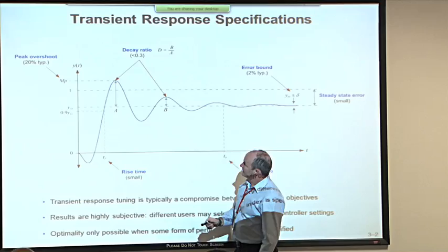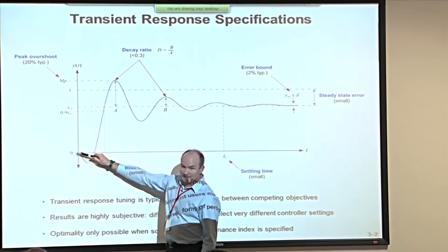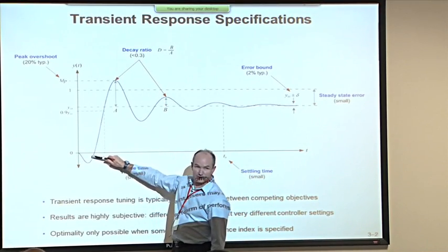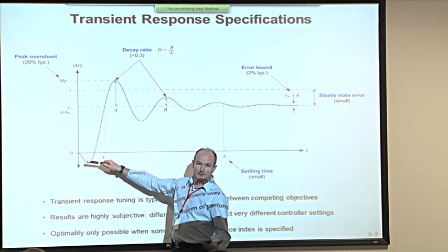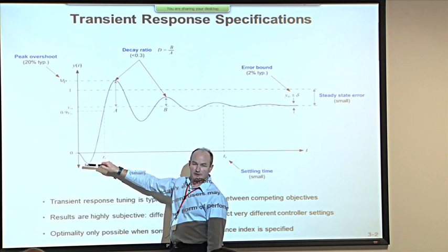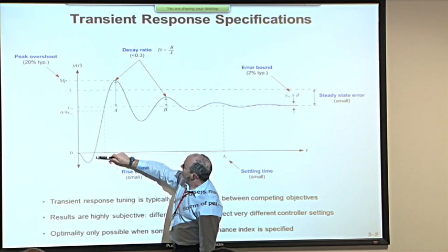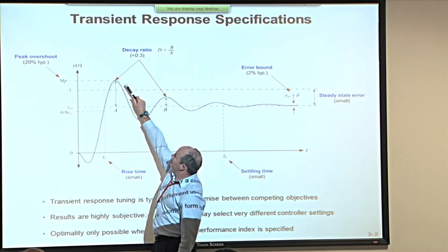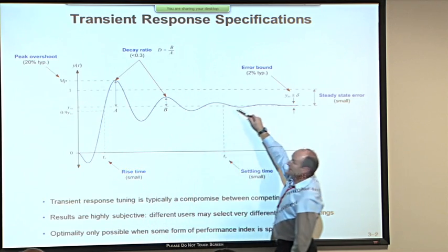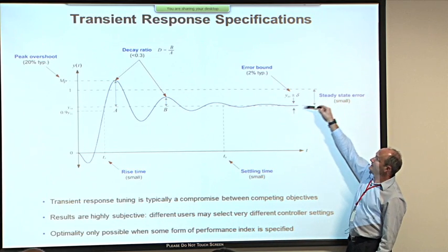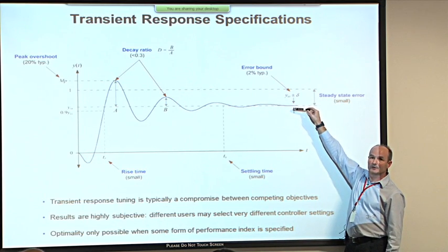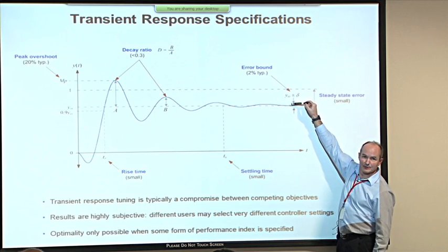This one clearly doesn't. The blue line representing the output has a sort of undershoot associated with it. Maybe that's a right half plane 0 indication. Then it rises up, overshoots, comes down, and oscillates. Eventually it stabilizes on a steady state value, which unfortunately is not the same as the input.